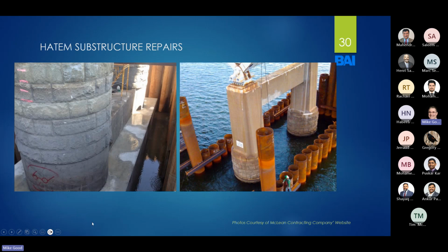So I said I'd talk a little bit about another sheet piling prevention. If you recall those undermined piers that were standing on this forest of what looked like toothpicks underneath them, this is the Hayden Bridge. The Hayden Bridge is Route 40, US 40, over the Susquehanna River up in Northeast Maryland. It turned out the scour analysis showed that under a 500-year flood, the 39 feet of soil that surrounded the piles that support these piers would wash entirely away.